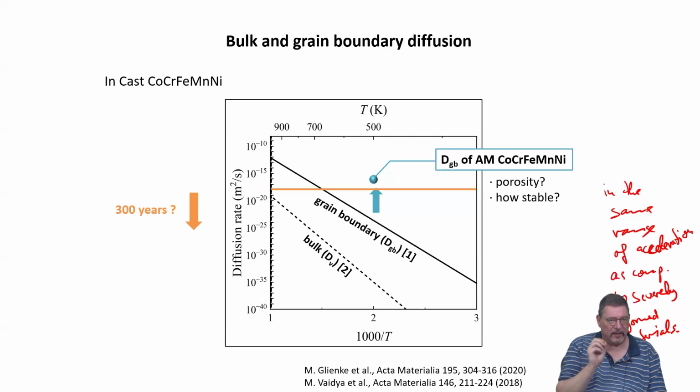So phase stability in additively manufactured materials is bound to be very different as compared to the same material in terms of its nominal composition, but produced by a conventional route, like doing some kind of liquid processing, homogenization treatment, maybe deformation swaging, and then again relaxation treatment.